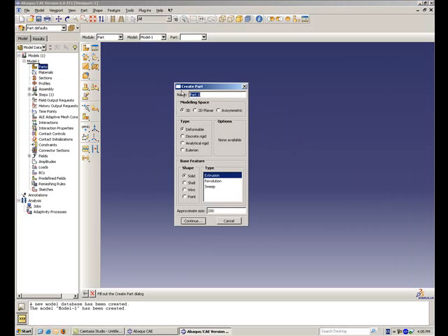In the model tree on the far left of your screen, double-click on Parts, name your new part Beam, and enter an approximate size of 300. The model tree provides a visual description of the hierarchy of items in a model and is explained in detail in Appendix B.